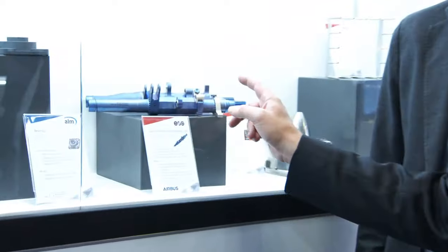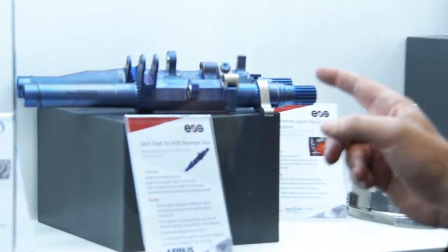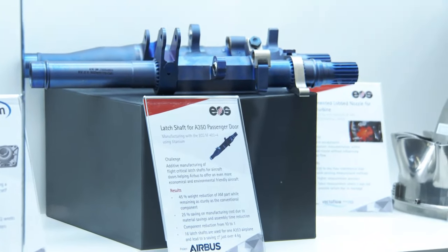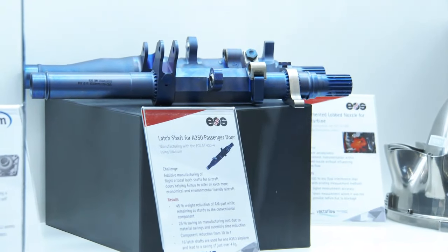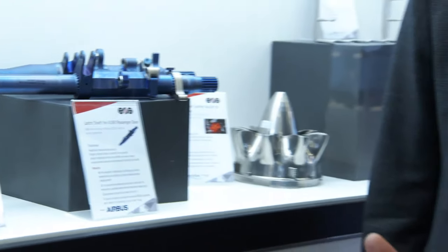It's not only the weight saving, which actually, as 16 of these parts are always in an airplane, are helping to save more than 4 kilograms of weight. But also previously it were 10 parts which had to be welded together. So now it is in one part. And the other thing is, again, together with all the software application, having it integrated into CAD/CAM CAE files for doing the data preparation and doing the experience, it helped Airbus to develop these parts way faster.